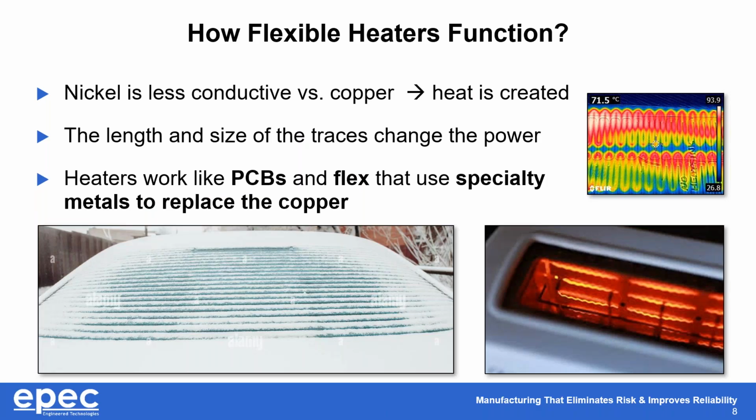So when we look at a new application, we spend a significant amount of energy working with our customers on the front end to better understand what you're trying to accomplish, to understand the input voltage and options that you have, if you have a current limiting source and whatnot. All of these are important when we size the heater. Failure to do so means the heater won't work right, or its lifespan may be jeopardized.